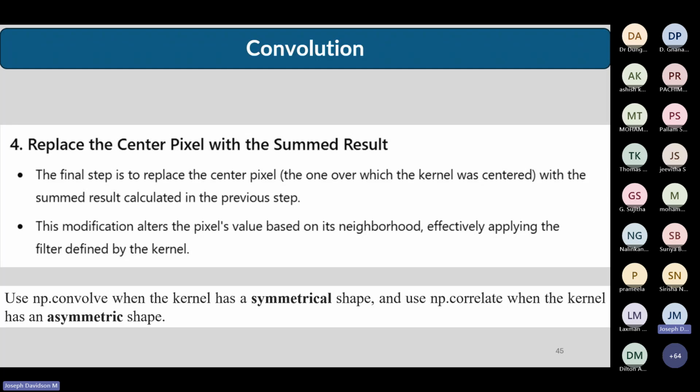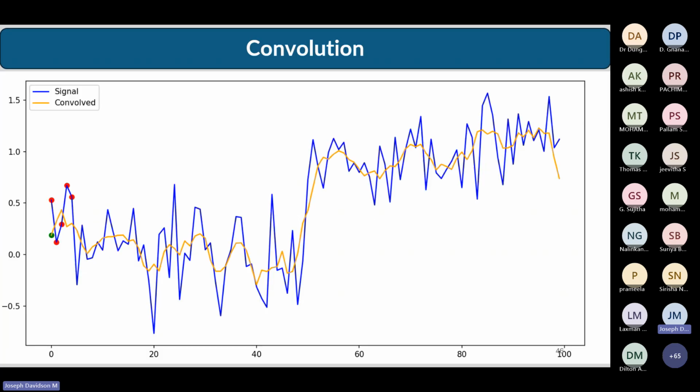Correct? Understood? So at a particular spot having a lot of intense values, you keep on trying with a moving average by taking additional points. You try to smoothen it and make it a bit more normal. Okay, so that is how it is done. So there was a signal, and there was noise, and we have used the convolution algorithm, and it is slightly smoothened now. It is following the same pattern, but its intensity has come down. Correct? This gold colored line is slightly smoother than what you had earlier, right?